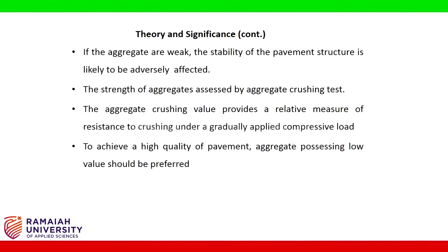The strength of aggregates is assessed by the aggregate crushing test. The aggregate crushing value provides a relative measure of resistance to crushing under a gradually applied compressive load. To achieve a high quality of pavement, aggregate possessing a low value should be preferred.